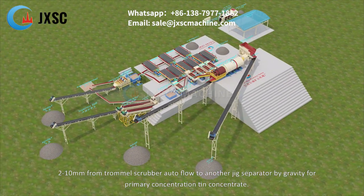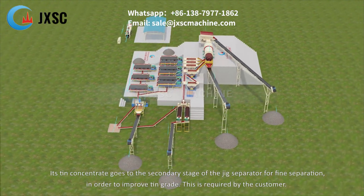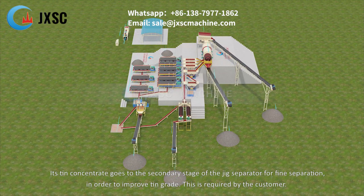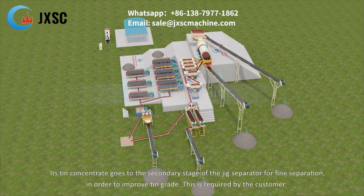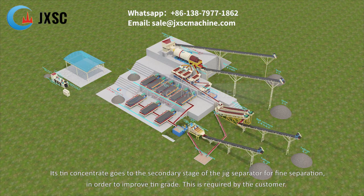2 to 10 mm from trommel scrubber autoflow to another jig separator by gravity for primary concentration of tin concentrate. Its tin concentrate goes to the secondary stage of the jig separator for fine separation, in order to improve tin grade, as required by the customer.